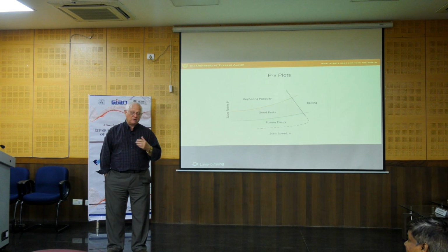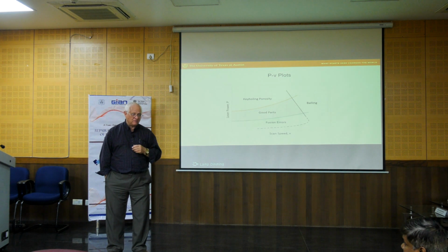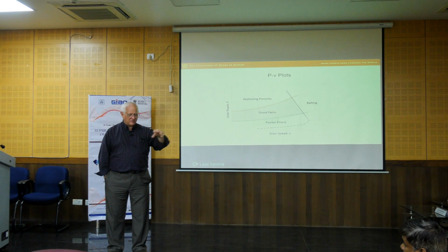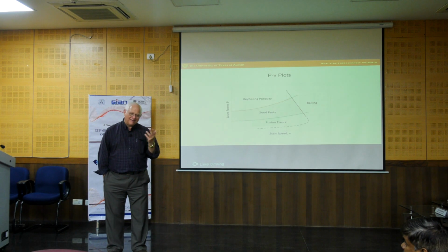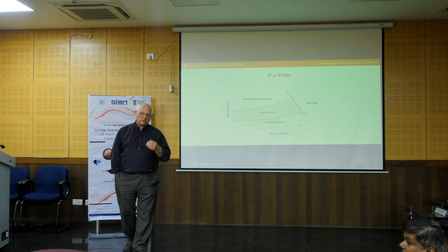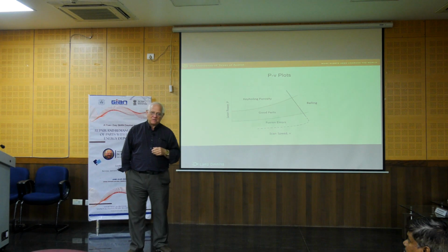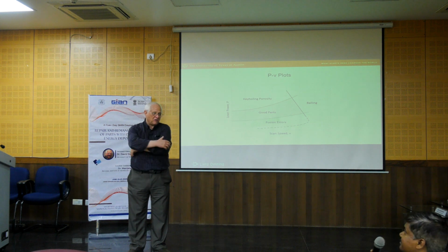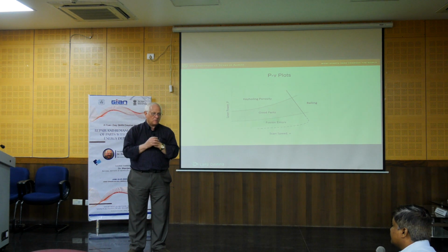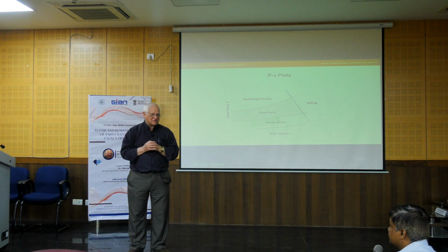But having said all of that, with DED there are some beautiful examples of functionally graded parts, typically done on a layer basis. Not really three-dimensionally spatially, but rather a layer of this material, a layer of a different material, and a layer of another material. But there's no reason that DED couldn't do otherwise. They make good parts. They function the way people hope they would in terms of the technology. So I think it's a very good area for the people that see it as important. It's a way to solve very specific problems. Yeah. Thank you, sir.